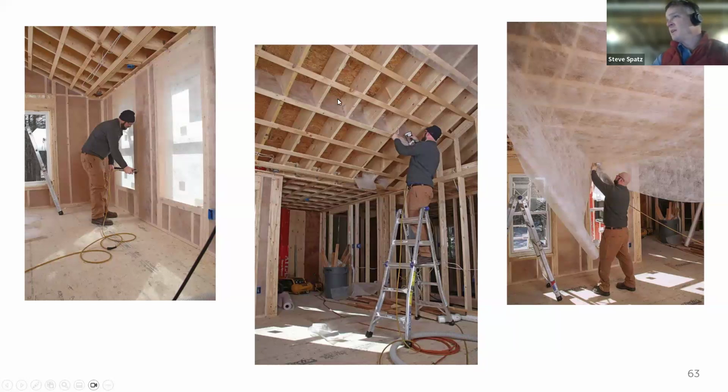When you have big depth cavities and huge expanses, this really comes into play, like with a deep rafter or a double stud wall. You need to start to isolate sections of those cavities in order to get density. You can't just take a wall that's 30 feet long by 8 feet tall and 12 inches deep, double stud, and fill that whole thing with cellulose insulation and expect to get density. You have to isolate cavities in order to make that happen.